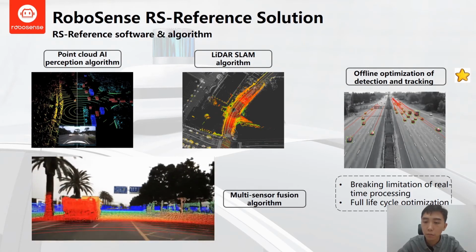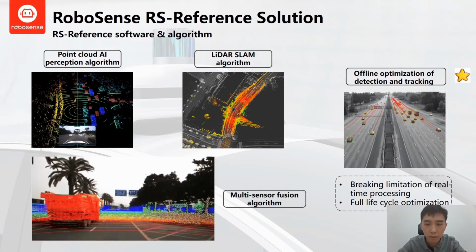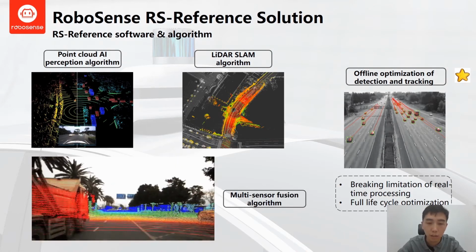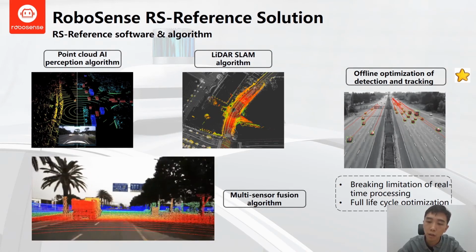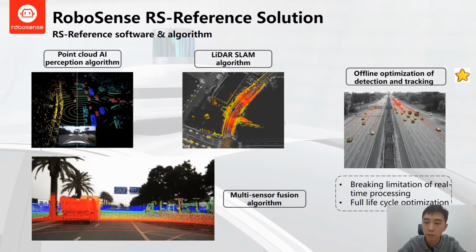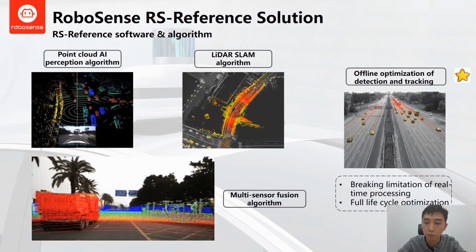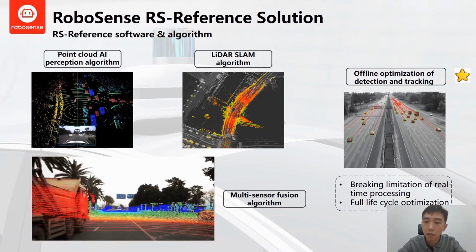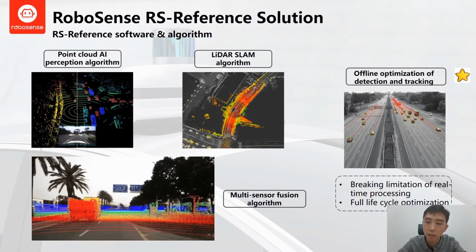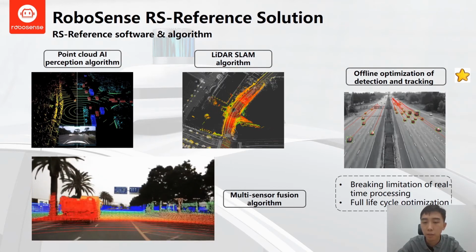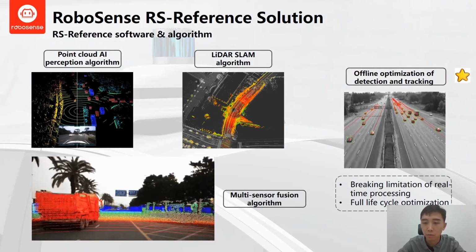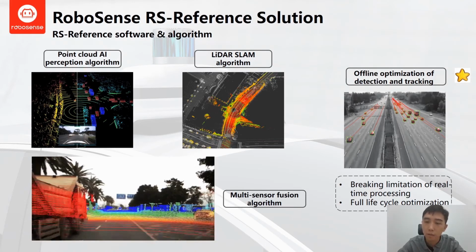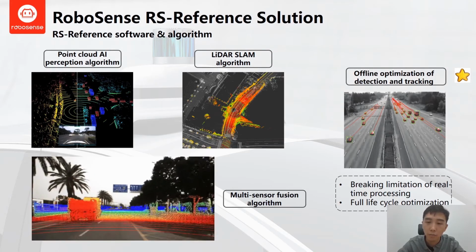And we also have other operations, like sensor fusion, or later control and decision. So maybe we want to finish the LiDAR perception algorithm within, say, 50 milliseconds. Also, there are usually limitations on the computational side. We may want to use an FPGA or some chips, so the computational power may not be that strong.